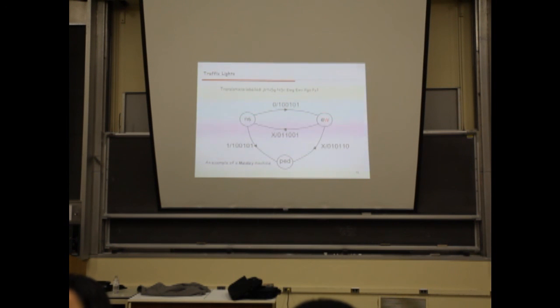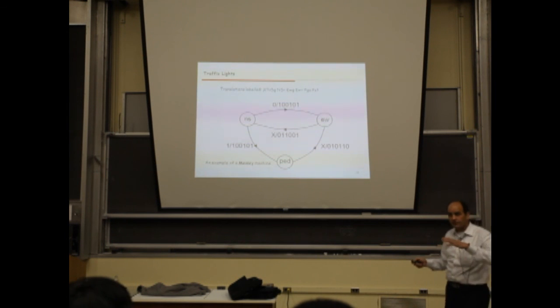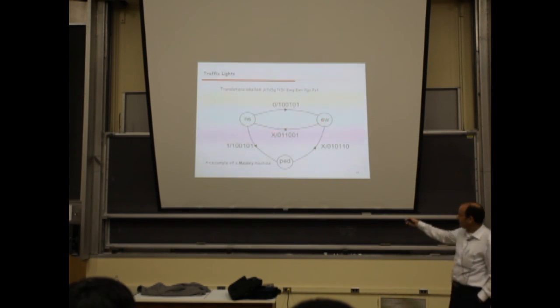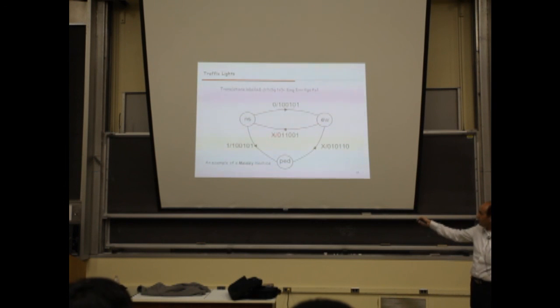Okay? When you reach this state here, now you are in the EW state, you wait for the clock, and then it doesn't matter if there is an input or not, you just have to go back to north-south. So 1 or 0, the system will just ignore it and come back to this state first.